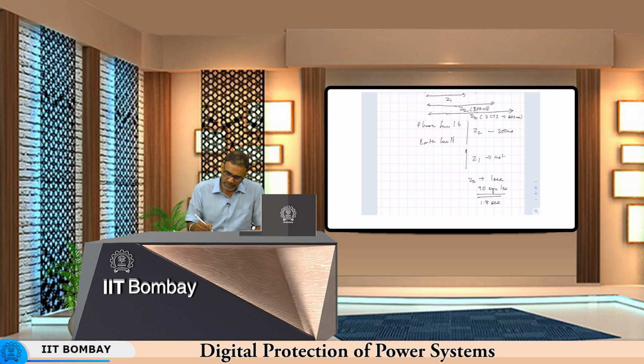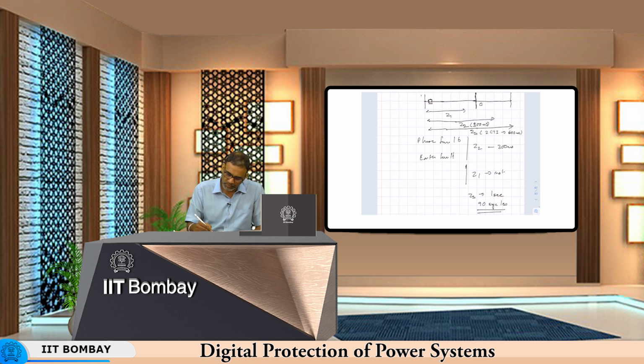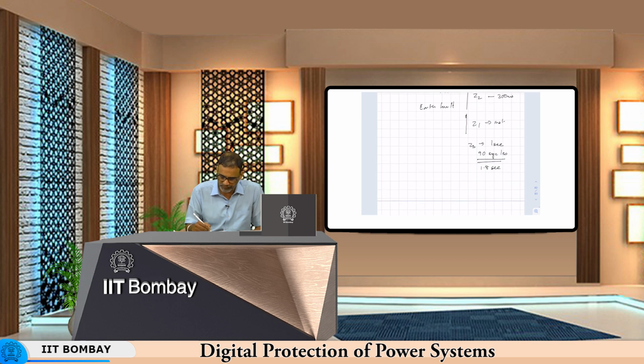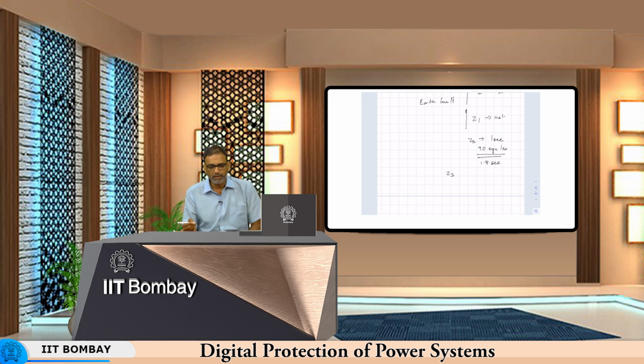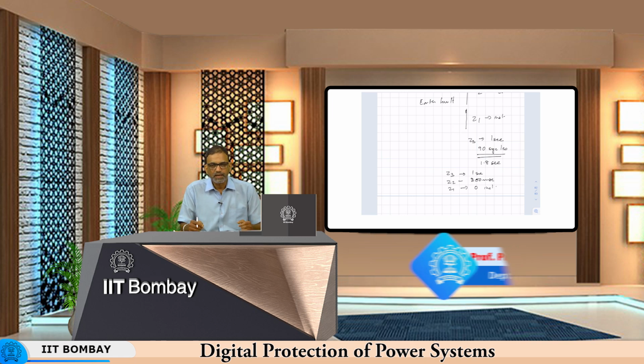If it is in Z3 but not in Z2 and Z1, it waits for 1 second. If it is in Z3 and Z2 but not in Z1, then it waits for 300 milliseconds. If it finally falls in Z1, then there is no wait at all, it will trip instantaneously. So we will stop here and look at more details of settings and other aspects of distance relaying the next time. Thank you.